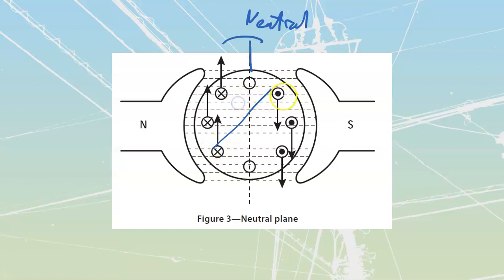I should actually draw it looking like this over here. Right now, its direction of rotation, we're forcing this thing up like that. We're going to have current that's going to be pushed through it like that. I've got current traveling through there, and it is going to move up, up, up. Eventually, I'm going to get up to here. And once this thing crosses and moves around to here, then we would have to reverse that direction of current through that same conductor in order to maintain the same sort of magnetic field that we would have off of it.